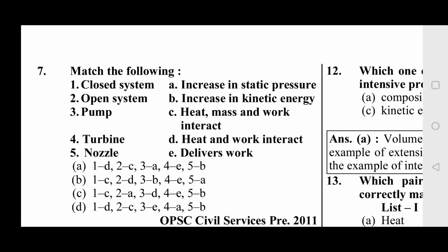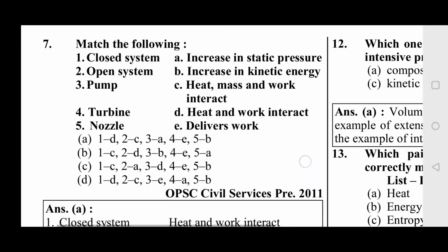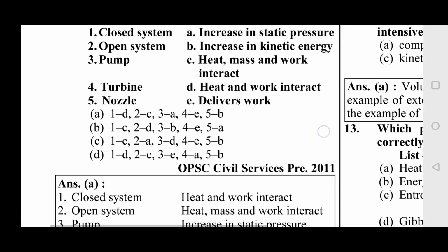So answer is C. Next, pump. Pump increases the static pressure. So that is A. Next one, turbine and nozzle. Increasing the kinetic energy, what does increasing the kinetic energy mean? Nozzle. Okay, and turbine? We have only one that delivers the work. So answer is A.